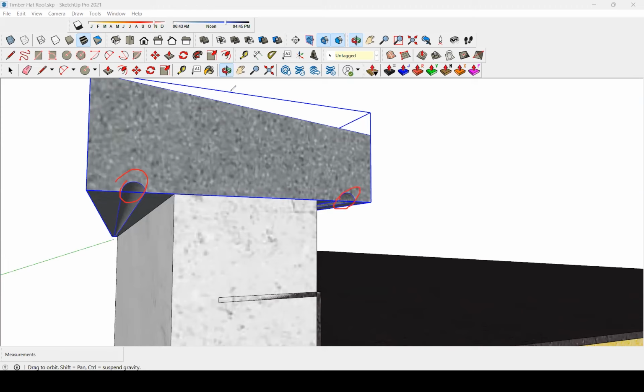I've explained this in a video before, but I will just briefly explain this now while I'm here. When the water is trying to roll off, it will go in this direction. If you don't have these drips, it will just flow down the face of the wall, and eventually this face will get very dirty and ugly.